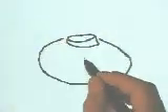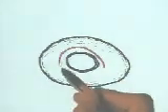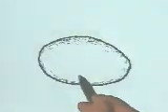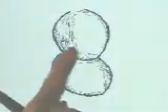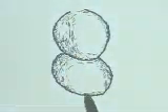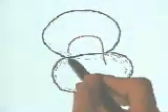If you want to remove unnecessary bumps, draw a closed stroke around it and scribble. Then the system constructs a new smooth surface. This operation can be used to remove a crease to smoothly merge the extruded surfaces.